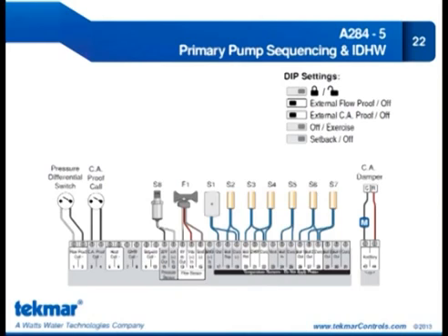We've seen that typically current sensing devices or current sensing switches are typical for proving flow out in the primary loop. And of course, as I mentioned too, if you want to use the flow sensor, there's a picture of the flow sensor connected up to terminals 13, 14, 15. So you can use that flow sensor to display flow and of course prove flow by setting that lower rail based on the flow at which you're going to prove flow.